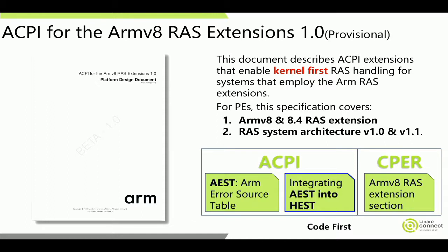But how to integrate this table into ACPI, we have 2 approaches. One is to put this table as a standalone table, just like the HEST table, like the BERT table. Or maybe we can integrate this table into HEST, like the GHESv2 table. So one of the companies has tried to implement this table in both of these ways.